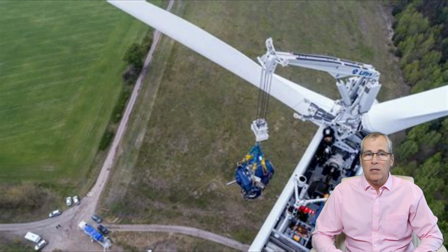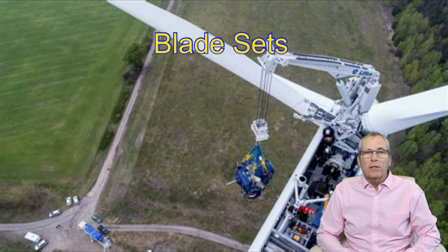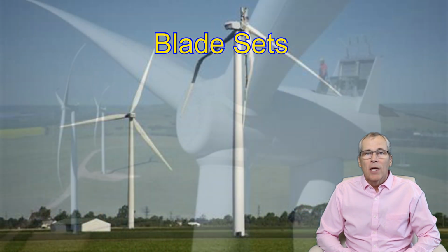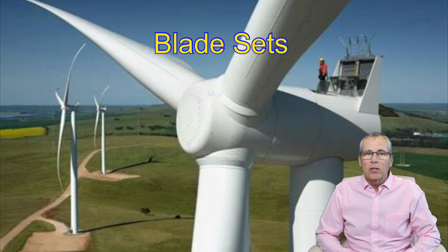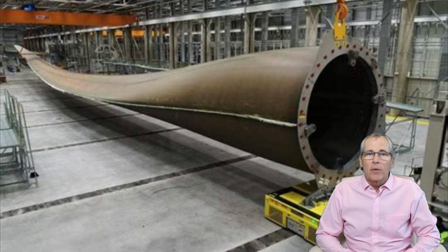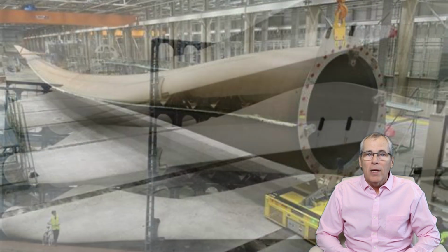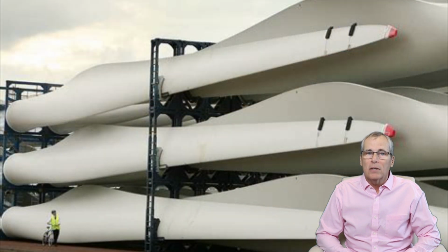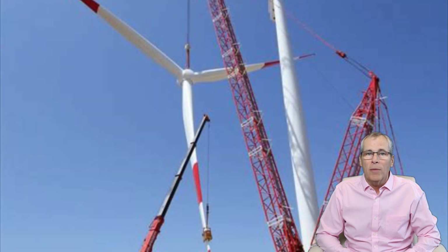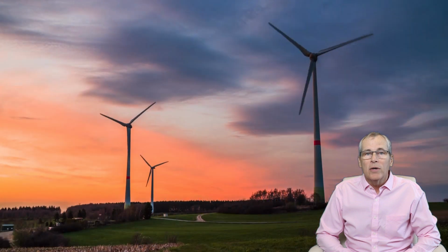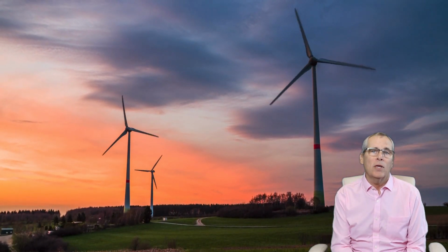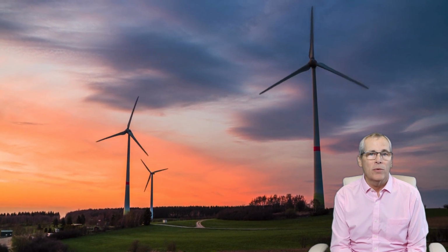and costly process. Whether blades must be replaced as a set versus repaired on an individual basis depends on several factors, including the extent of the damage, the age of the blades, and the cost of the replacement versus repair. If the blade is significantly damaged, such as being cracked or broken, it may need to be replaced. In such cases, it's often recommended to replace the entire set of blades to ensure that they are all the same age and condition. This helps to ensure that the turbine is operating at optimal efficiency and to avoid any potential imbalance that could cause damage to the turbine in the future.